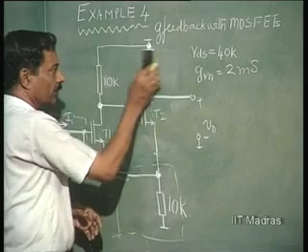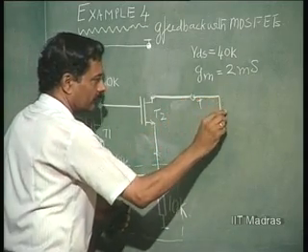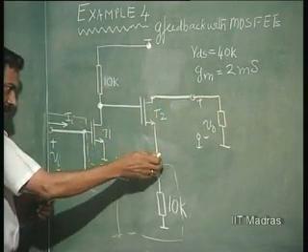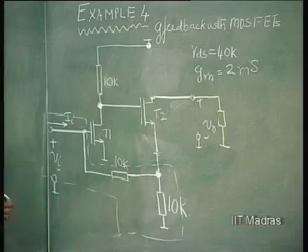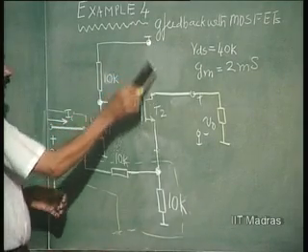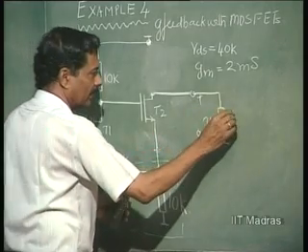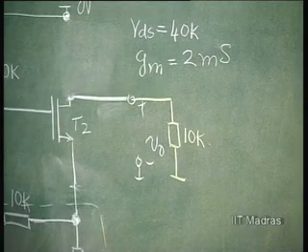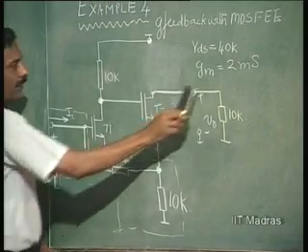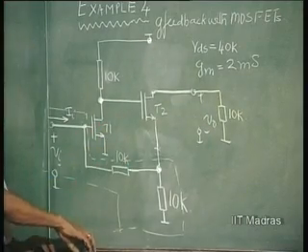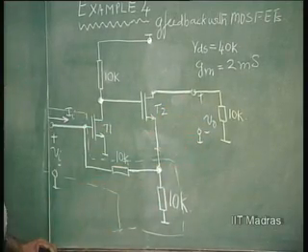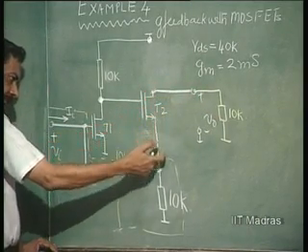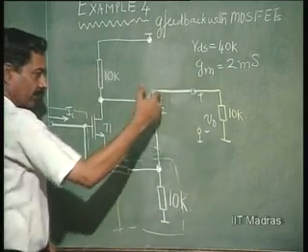So, the load that you put must be put at this point, so that this load comes in series with the amplifier as well as the feedback network. So, this connection from here to ground is simply lifted and put here. So, this is considered as the load. In addition, actual load may be there, right. In this problem the actual load is not given, just the RD2 has been given as 10 K, that has been put here. So, now the current is common to the load, the amplifier and the feedback network. This is how it should look.